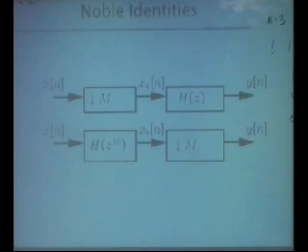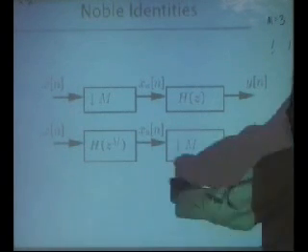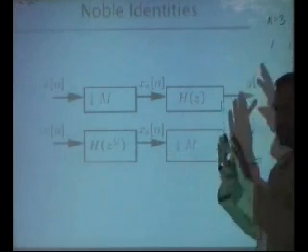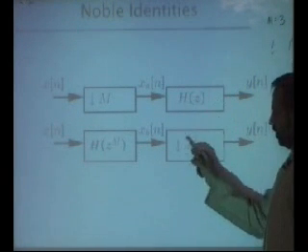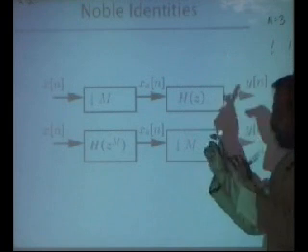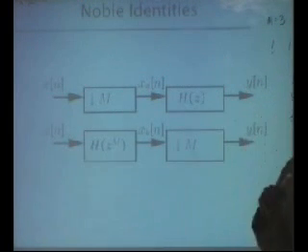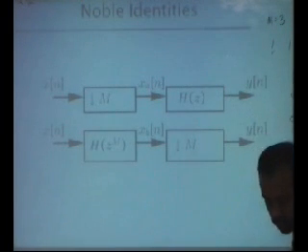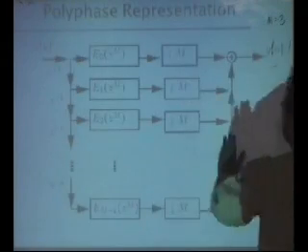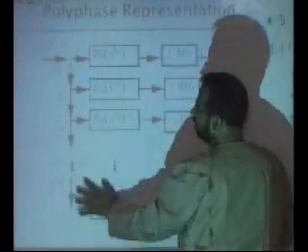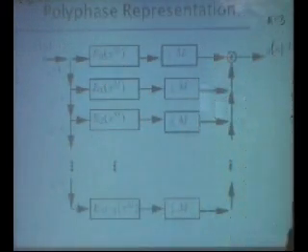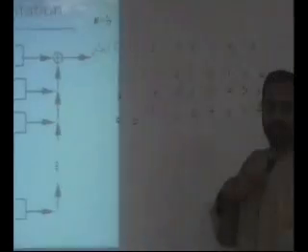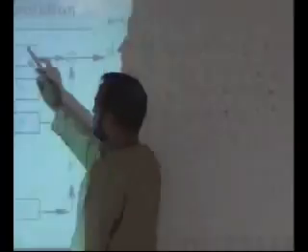It is basically, we are saying, if you are in a situation where your filter has periodic zeros, a stream of zeros, and you are decimating, then you can play this trick. And how this trick helps is that if I bring this M on this side, what will happen? It will eat up this M, right? So it will eat up all these zeros, which is good for me, and this will come here.